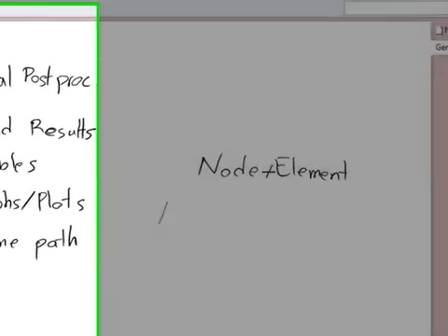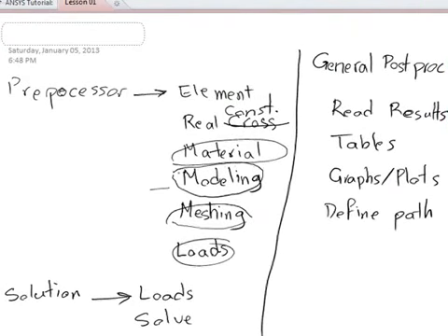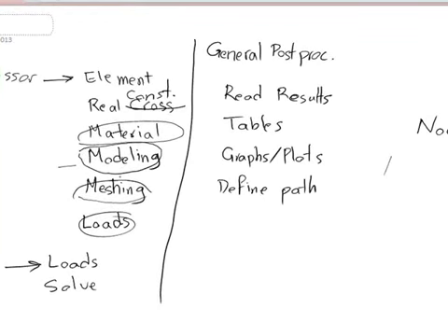So when you're doing your modeling in the modeling section, you're making areas, volumes, lines, and stuff like that, which ANSYS cannot understand how to solve loading on a surface or an area or a line. So if you have anything but nodes and elements, you have to do the meshing to divide your, say, area or volume into a number of elements which are defined by some number of nodes, and then ANSYS can use these nodes and elements to do the analysis for you.